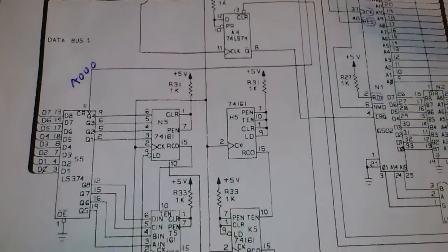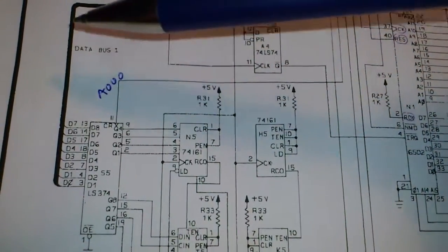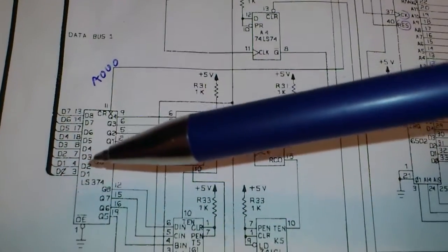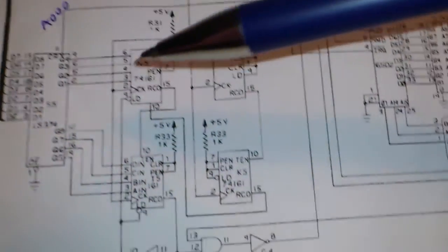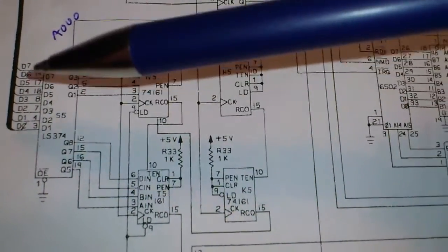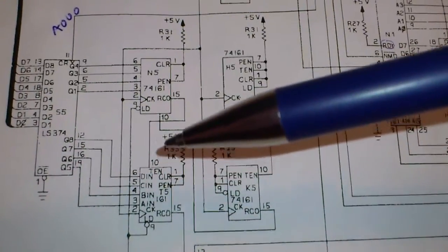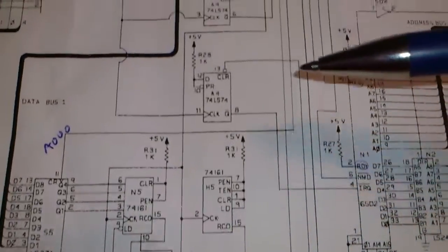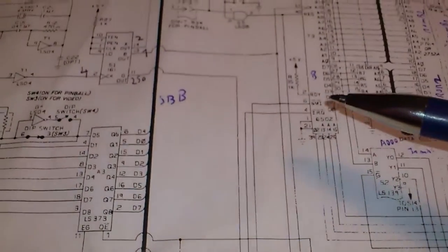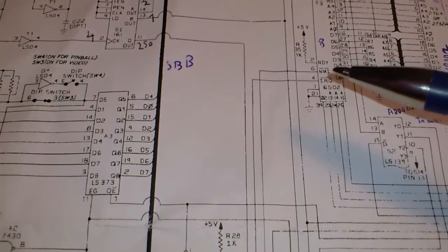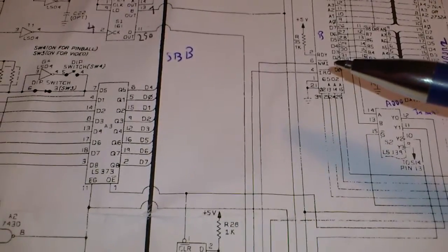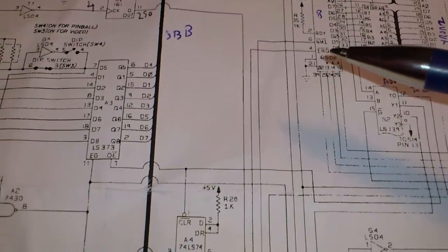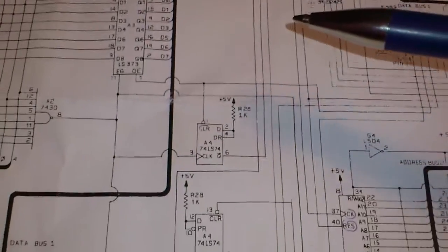And how it works is that the CPU on the data bus, once it's selected, can send out a seed for this counter here. And then when the seed is loaded, the counter counts up until it overflows. And when it overflows, it actually generates a non-maskable interrupt on that CPU here, telling the CPU the timer has elapsed, the period is over, do something. And this is repeated all the time.